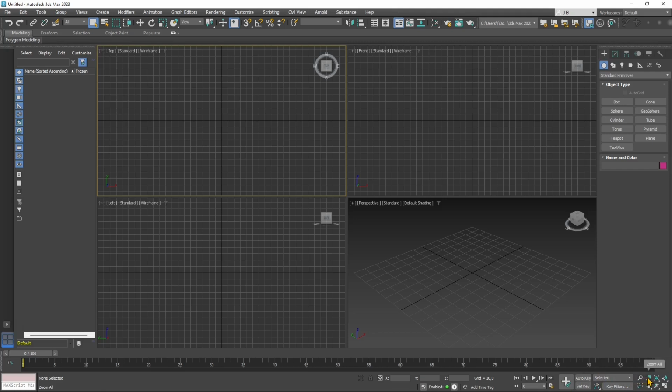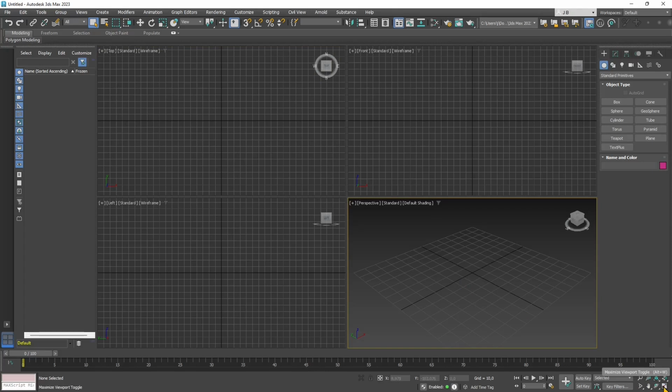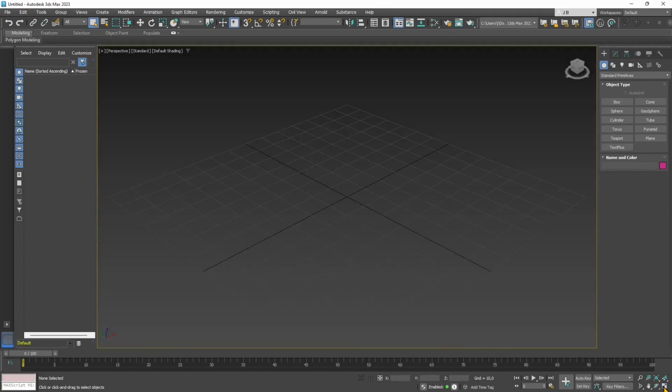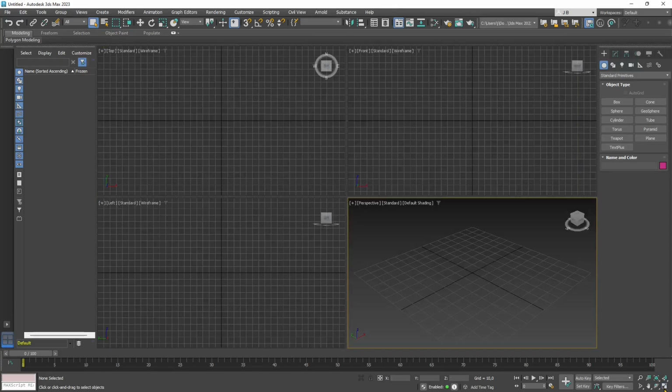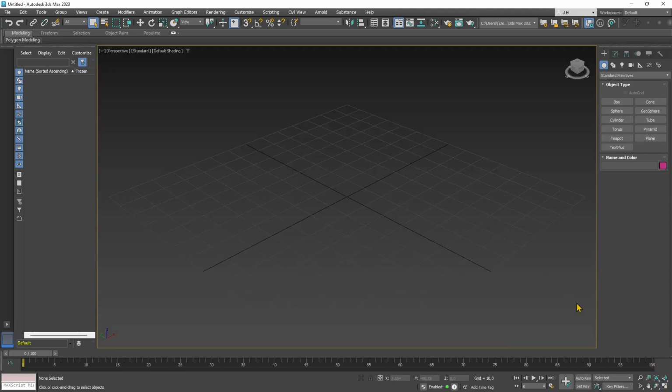And on the bottom right, you have some navigation tools that are really important at the beginning when you need to navigate your scene. So first of all, we're gonna address all these really basic and important parts of the interface, like navigation, selection. And this one here, really at the bottom right, this is to maximize and minimize. This is also really helpful. Sometimes you will start with this big perspective here, but working just with the perspective is not suggested. It's usually better to work in 4 views so that you can actually see the project from many different angles.